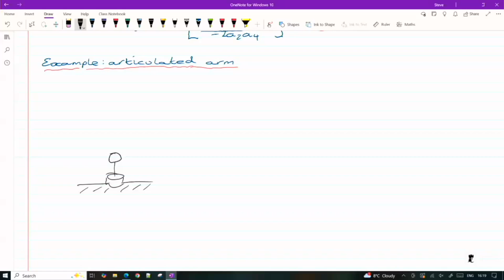So you have two joints at the shoulder, and you have a fixed link, and you have a rotational joint at the elbow that's to another link of where the end effector is attached. And for you, there'll be a small displacement, and this is a claw at the end. Okay, so you need to take that into account when you're working out where to place your Dobot to interact with the objects that you're told.